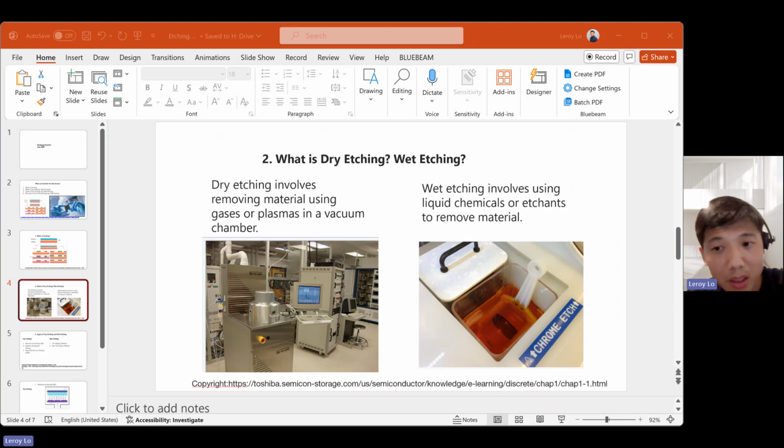Dry etching is now the most commonly used type of etching because of its preciseness. This process normally uses neutrally charged high energy ions to etch the target surface. We generate these ions using a radio frequency field to convert reactive gases to plasma. So we basically use plasma to control the process and remove the material after the mask.